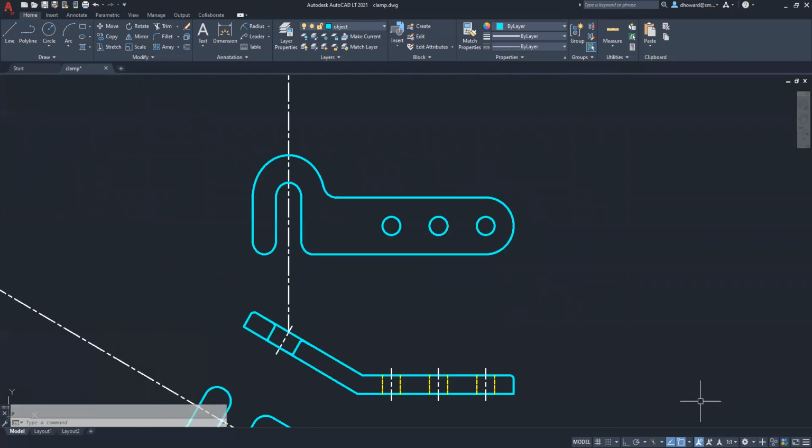Not an easy thing to do, blending one ellipse into another, which is what we did here, making one ellipse tangent to another. Tricky. It did require a little eyeballing, if you will. Not critical. None of this is going to be dimensioned. So no foreshortened objects, and none of these arcs or ellipses we made would ever be dimensioned.